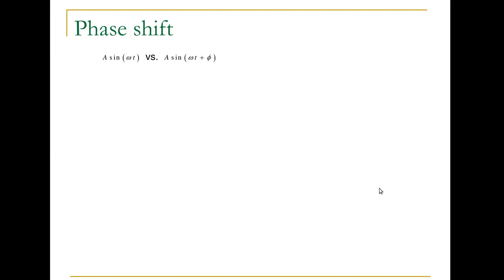Now there's also phase shift associated with this because we have complex gain. Let's look at the effects of phase shift on the output signal. If our input is A times sine omega t, then our output is going to be some amplitude times sine of omega t plus phi. Since we're only looking at the phase shift, we'll just say that there's no change in the magnitude, but the phase is going to be shifted by the angle phi.